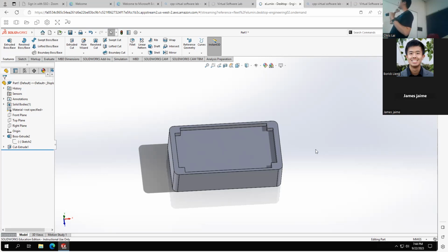And I think another thing I want to emphasize is being able to make what you want with the fewest features possible. So what I'm trying to say by that is, for example, if I were to make a really simple cup, how would I do that? I would make a circle, then extrude it, right? And then I'll draw another smaller circle, then cut through it, and that would get me my cup. But it's possible that if I had a cross section of a cup, I could actually just rotate that instead, and that would get me the cup instead of doing two features.